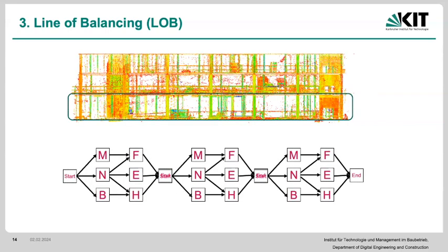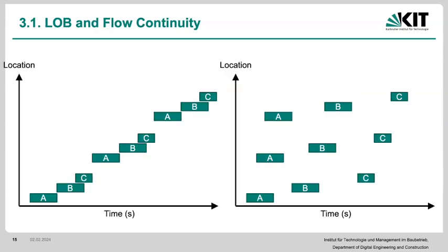Essentially, instead of having all of these activities for the first floor, all of these activities for the second floor, all of these activities for the third floor, or for the third division or fourth division, we can recalibrate and reorient these so that we can optimize for continuity. So how does that look? It looks something like this, and this is not always possible, but there are some tricks that we can do, dependent upon how we do the subdivision, to optimize for the flow as well. But for this, we're just talking about some simple examples, let's say linear construction.